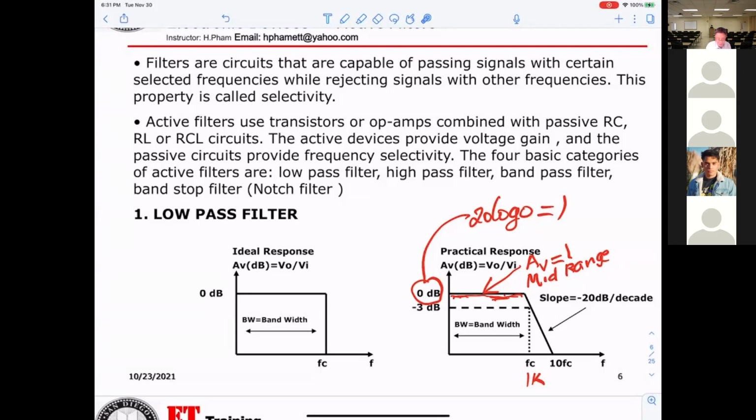And when you go to the cutoff frequency, at this point, I've given you 1 kilohertz, for example. Output now will be going down 3 dB. See that? You understand at the critical frequency, but if you want to calculate it, you have to take the input times 0.707 in order to get the value of the output.